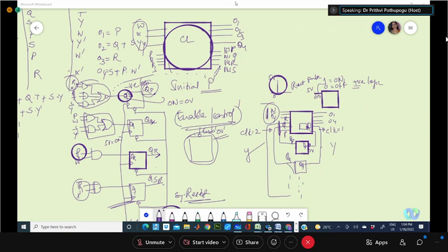Okay, first of all, you visualize the door. To the front side of your door, that means the frame, there will be one sensor, and inside the frame you have another sensor. 2 sensors will be used. If the outside sensor senses an obstruction, it will take it as an incoming candidate, so it will count in the up direction.